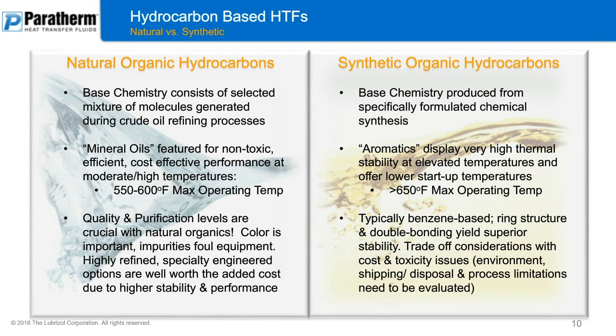You'll achieve operating temperature maximums above 650 degrees Fahrenheit. But that benzene-based ring structure is really the key behind this chemistry here. The double bonding yields superior stability. It's able to handle the heat energy much better, so it allows you to get to higher temperatures and get longer lifetime of the fluid.